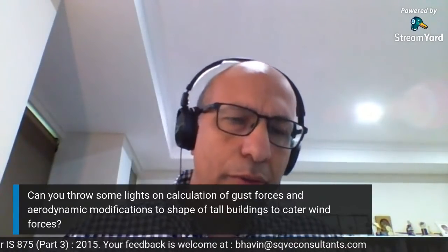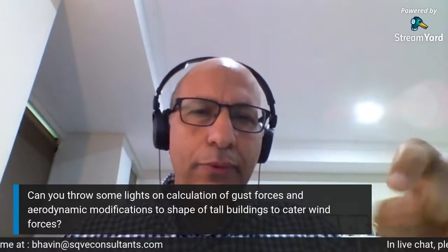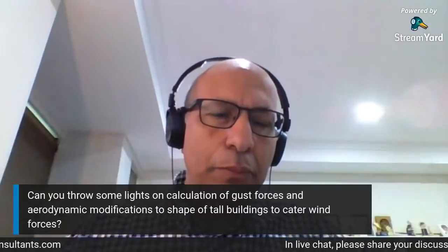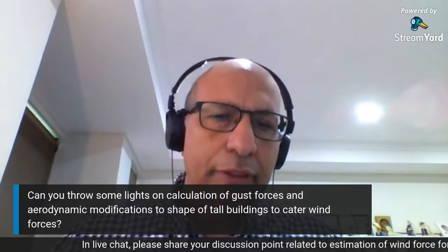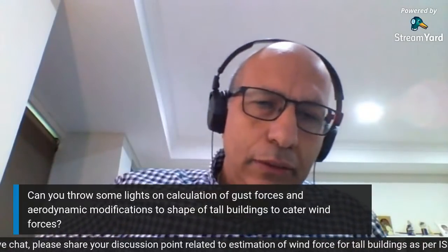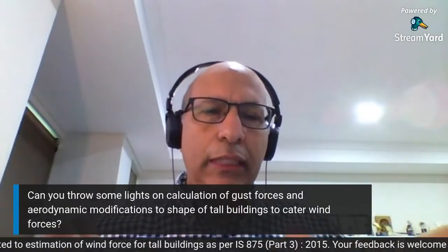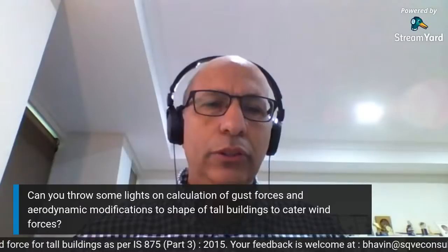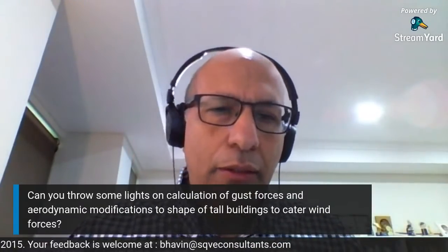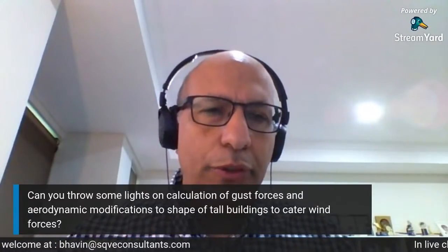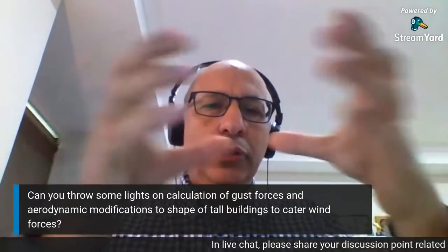Stepping is not the only solution. Corner treatment, like putting steps at the corners themselves rather than complete steps in plan, is effective. Roughly half as effective as complete steps, but still quite effective. Or changing the shape, so basically changing from a square to an octagonal shape or circular shape, or even changing from square, circular, back to square.